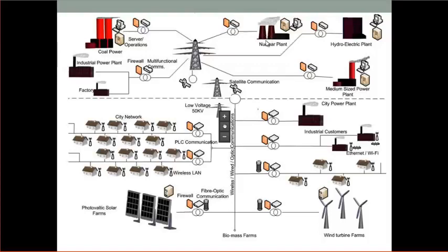But you can tell a nuclear plant, I need you to make 1,000 megawatts, or I need you to make 2,000 megawatts, and it'll make that. And maybe every other year you take it offline for a couple of months in the spring or the fall to do maintenance on it. But for the most part, it makes power when you tell it to make power. Same thing for your coal plant. And then you have the little gas turbines. The neat thing about a gas turbine is it's like a big jet engine with a generator on it. You can push a button, and in 15 minutes you can be making 150 megawatts. So that afternoon peak comes, and at 3 o'clock you're going to need the extra power, so you start up that gas turbine and start making some power.